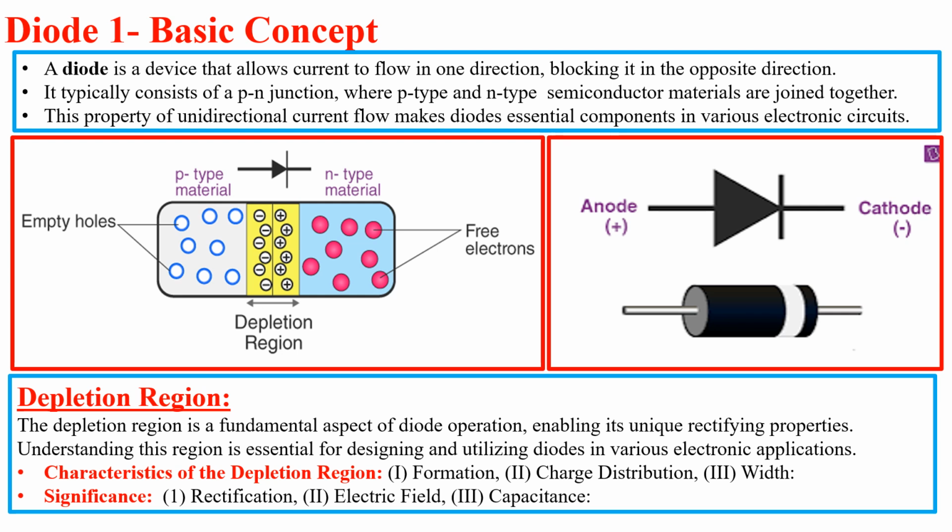A diode's construction is very simple. It is typically made of a p-n junction, where p-type (positive) and n-type (negative) material meet and a junction is formed. When the positive side, which is the anode, is connected to the high voltage, and the negative side, which we refer to as the cathode, is connected to the low voltage, the diode conducts electricity.